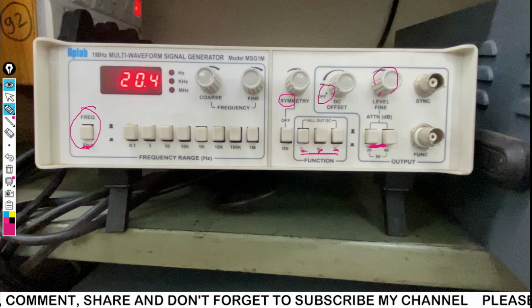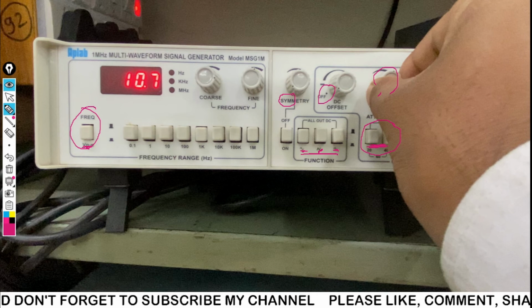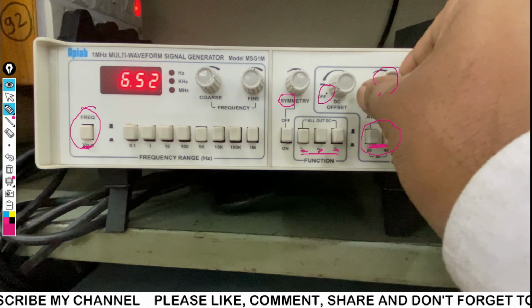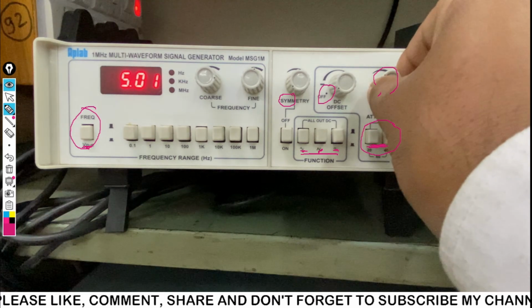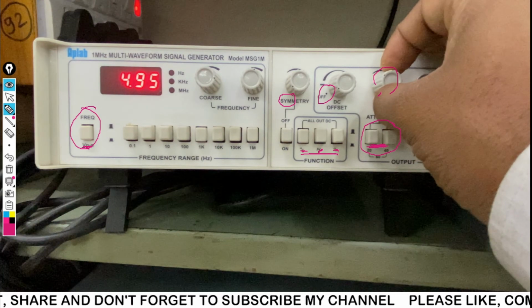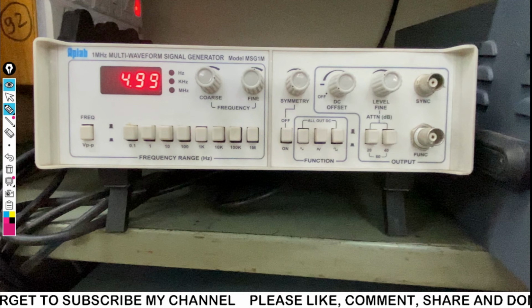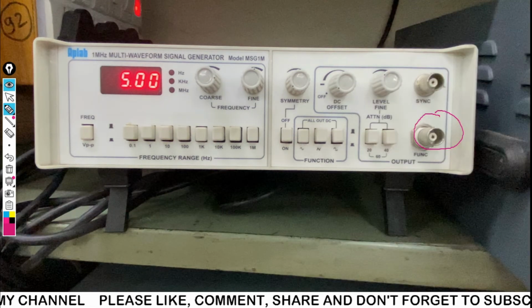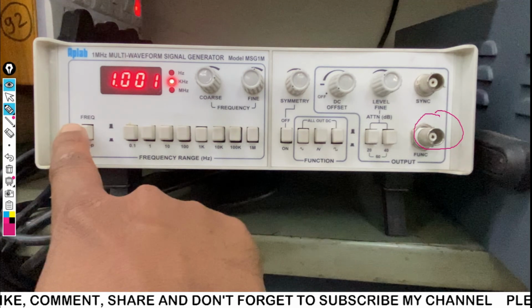Whenever we want to select a particular voltage, we select this combination of 20 and 40. If I have to adjust to 10, I have to release both of these, and then adjust towards the nearest value. Suppose I have to adjust 5 volt, then I adjust using this level button to approximately 5 volt or accurate 5 volt. We need to adjust the level very cautiously so it becomes 5 volt. Now this function generator will create 5 volt and a frequency of 1 kilohertz. So this is the way we can set amplitude and frequency.